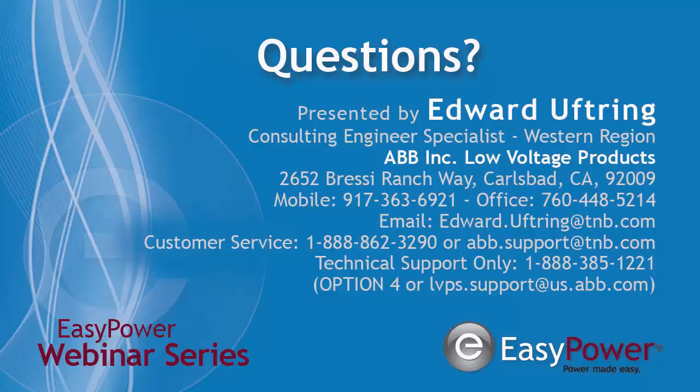So as you're going up in voltage, your current rating has to go down, depending on your application. So if you have 480 volts, then it becomes a maximum of 35 KA. A lot of the breakers are usually universal voltage, so you're going to have one that's 240, 480. In this example, you have one that goes from 240 to 600, but each one of those voltages has to carry its own current rating.